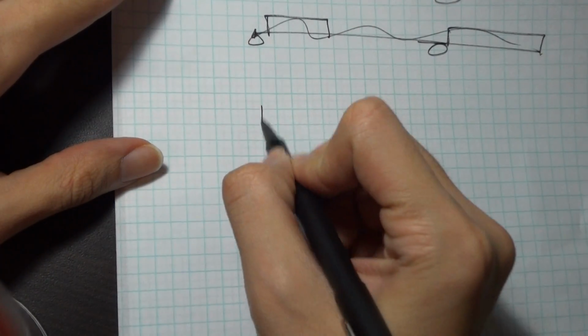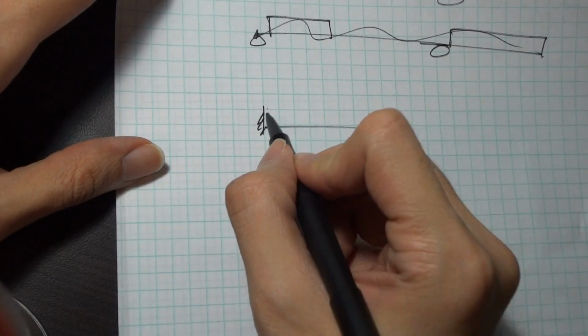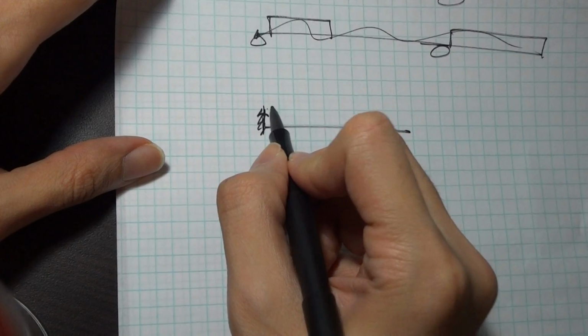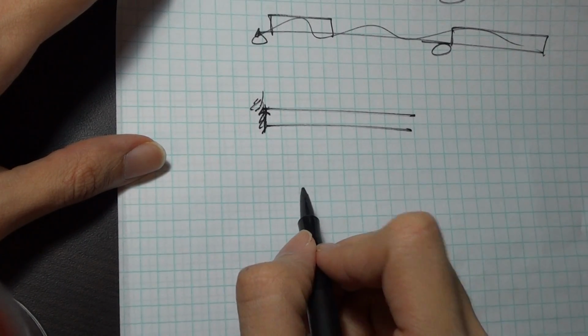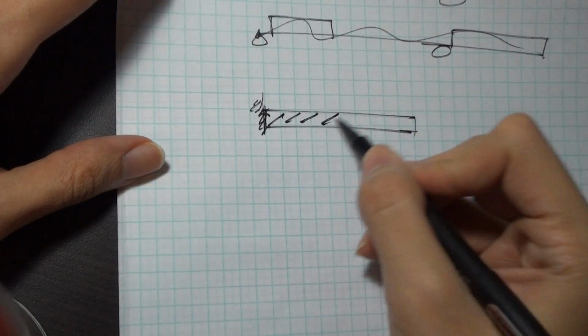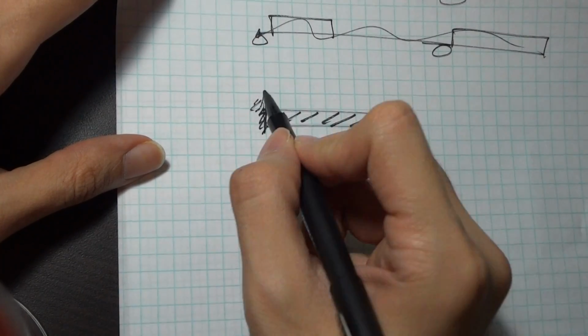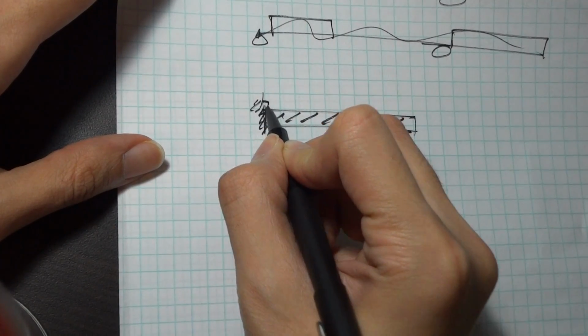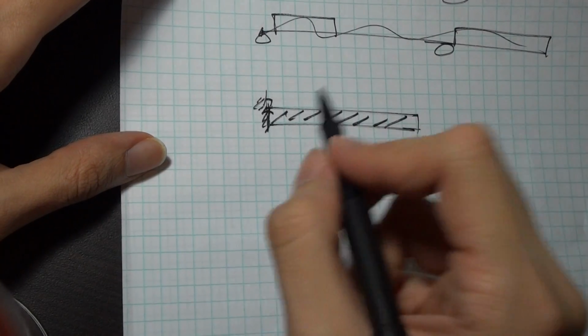For example, if I have a cantilever and I want to find the influence line diagram for this, I raise this point up by 1, and I just draw this. This is my diagram now. I've literally just raised this point up by 1. The boundary condition that I had to obey was that I have no rotation. This has to maintain a 90-degree angle.